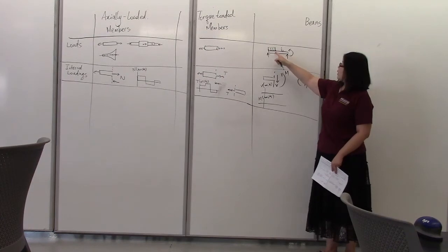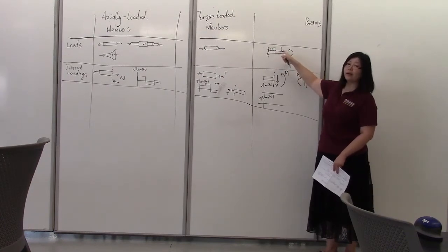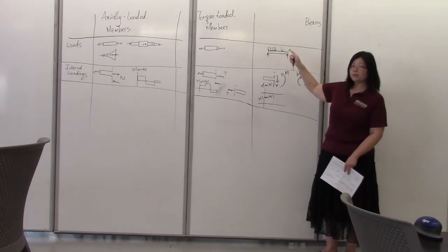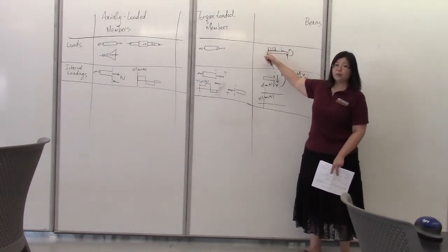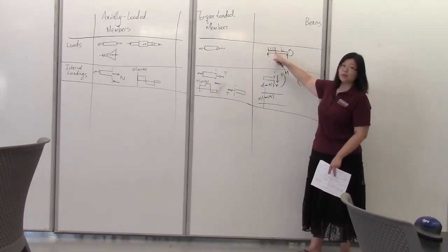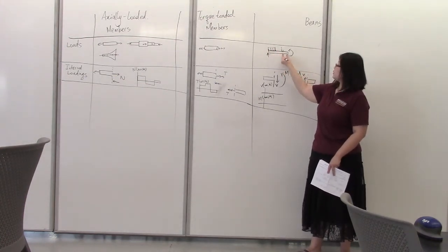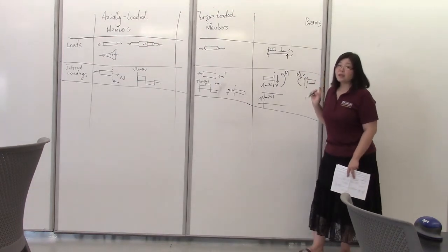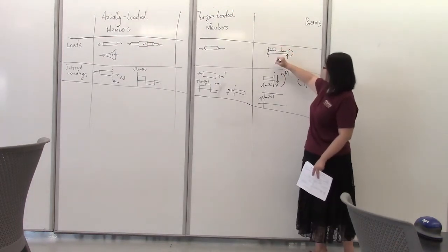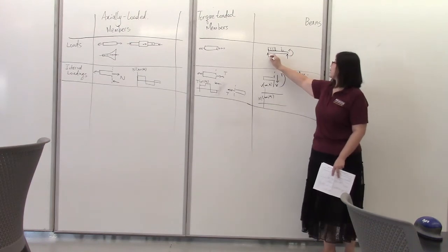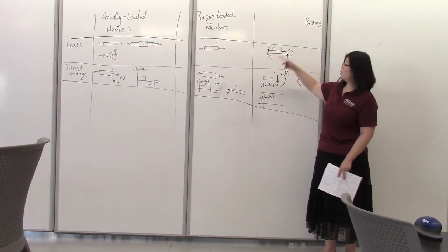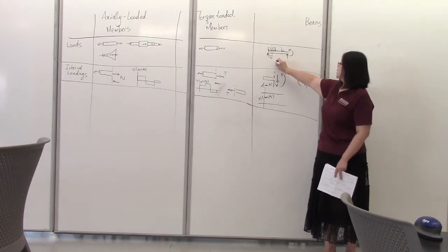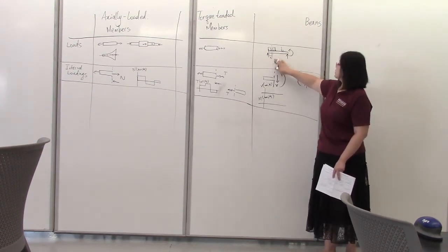So the division points are wherever you have a load applied, either a point load or a bending moment, or where you start to apply a distributed load, or where it ends. So in this case, you would have to divide the beam into 1, 2, 3 segments. For each segment, you will make a cut anywhere in between at a generic X location. Now your X could be defined from the left end of the beam, or from the right end of the beam, or from somewhere in between, from a division point, for example, as well.